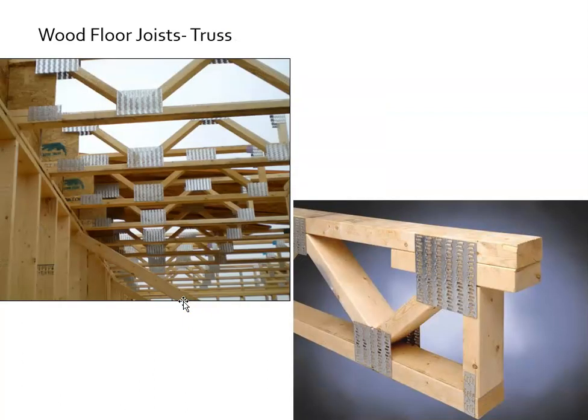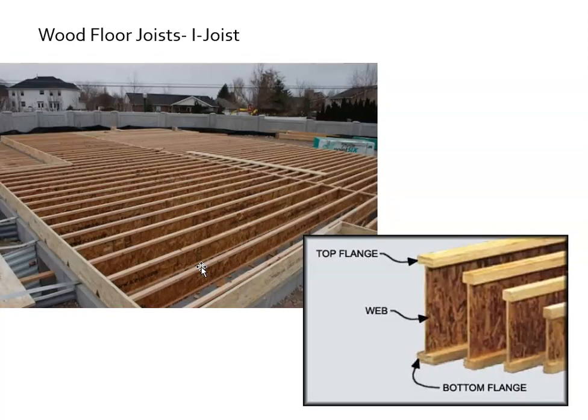And wood trusses, also very popular. Wood trusses allow for wiring, and if they're deep enough and big enough, they could allow for HVAC ductwork to run through. Pipes could definitely run through. So it provides a plenum if we're in a finished basement and we have to run utilities, mechanical things above the ceiling here. This is the best option really, because generally, there are rules and regulations to cutting into solid pieces.